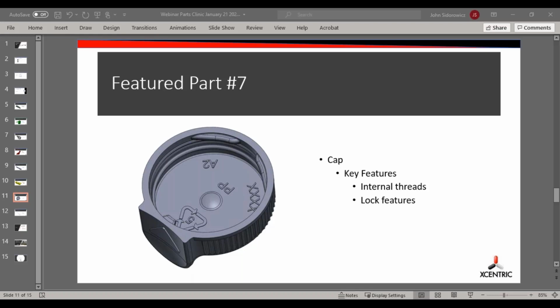As for prototype parts, do you do any first shot adjustments, or is that only for higher volumes? Kind of depends on what adjustments we're talking about. If there's a problem with the tool itself, then obviously we work through that during the tryout run. If there are any issues with the tool, some flash, we'll try to make those adjustments ourselves and get good parts. But again, it just depends on what we mean by that.